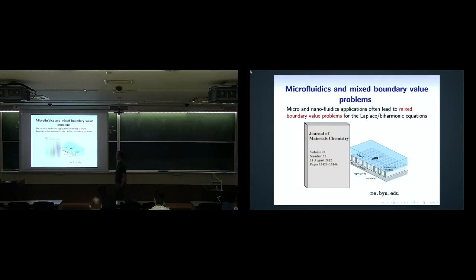So this is microfluidics. And this is a silicon chip. And in here, there's increasingly lots and lots of very dense electronic components, getting increasingly dense as we improve our technologies. But what it means is it's producing more and more heat. And in order to try to cool these, what people have done is they've made the tops of these chips, they put these little pillars and posts. Okay? Now, by the way, there's normally a top on here, and what you're doing is you're pushing liquid over these microchips with the hope that the heat will come up into the liquid and be transported away. It's a heat transfer problem.